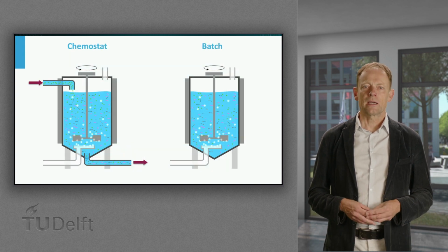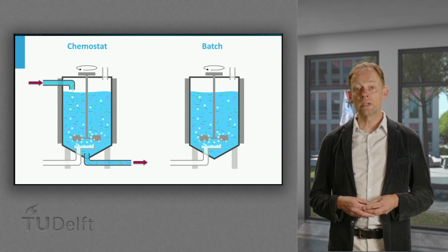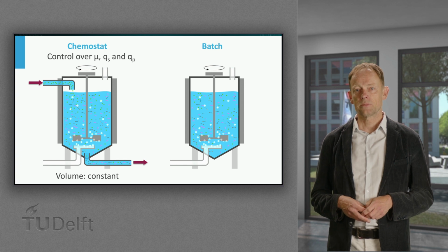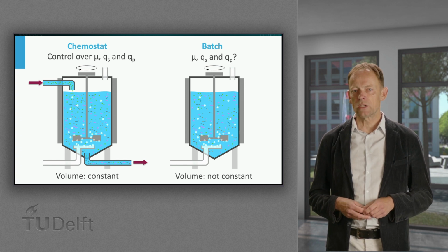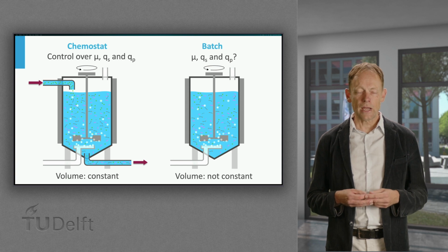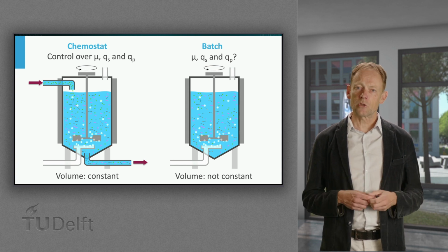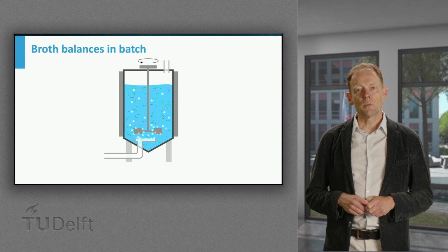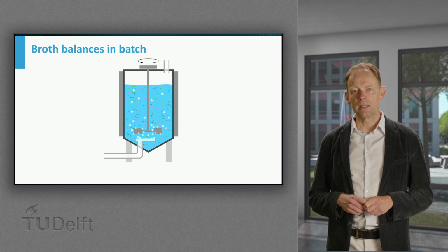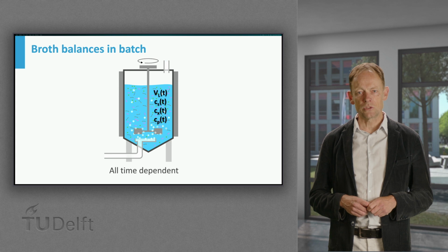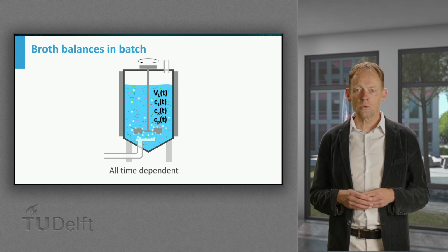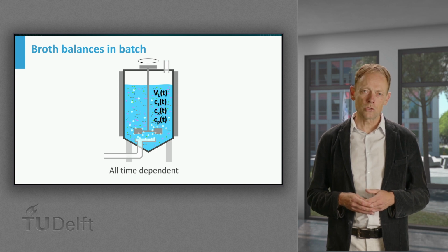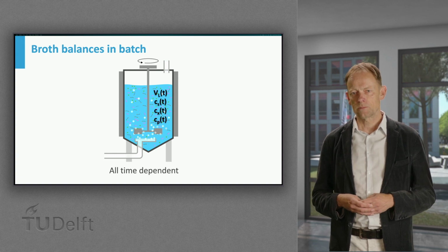In industry or academic research, chemostats are used as research tool, but for high throughput screening, often batch processes are the standard. Also here it is key to calculate the Q rates from balances, where accumulation equals reaction, and the transfer term should be added for gaseous compounds. It is important to realize that all variables are time dependent and the volume is never constant due to titrations, exchange of oxygen and CO2, and evaporation, and therefore we must use the total amount of compound in moles or kilograms and not their concentrations.